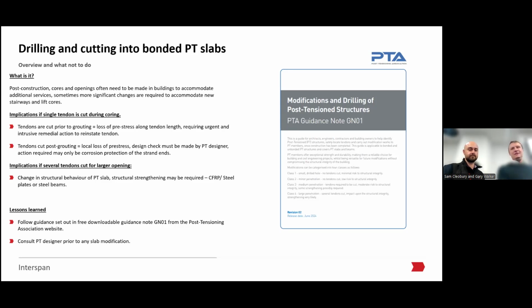It's the same with PT slab. You've got an extra layer: you probably need either your PT contractor who carried out the work or another PT designer or contractor to review the post tension design if the structural engineer is not experienced in that, because post tension slabs are designed for the bending moments that we're expecting, and if we cut a huge hole in one big bay, bending moments will change in the end bays or the promoted bays or whatever,